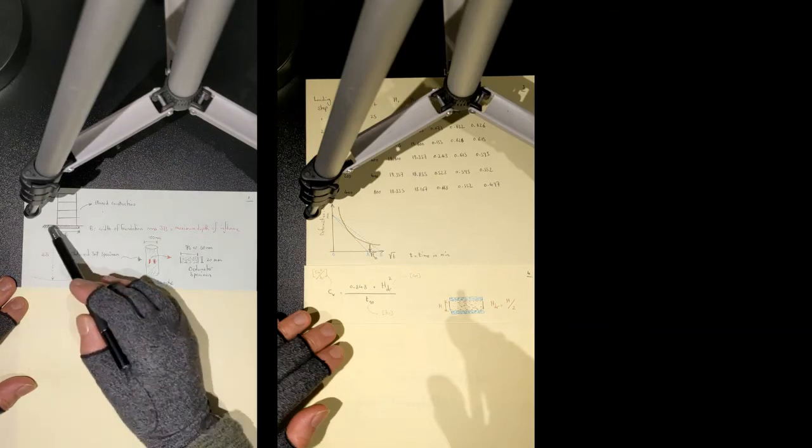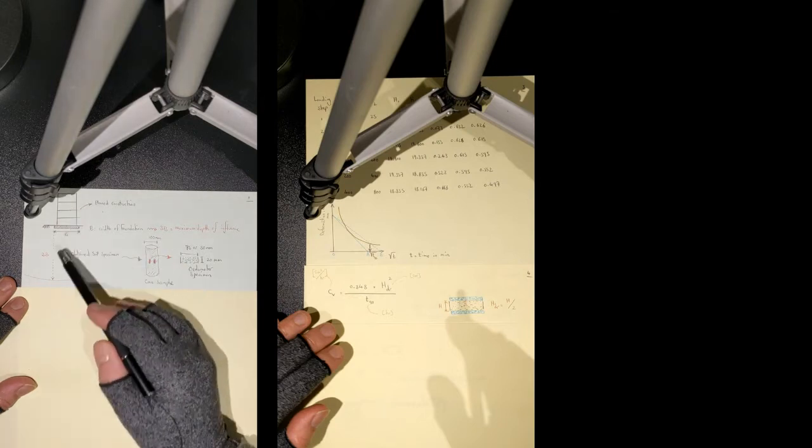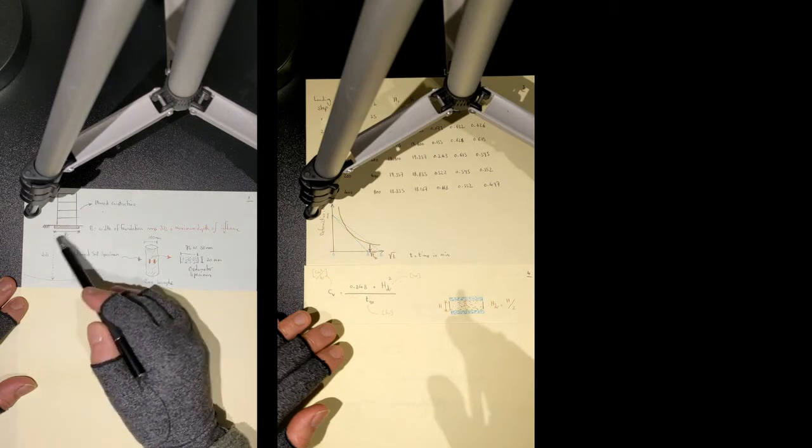and the deepest point in the very bottom of this circle has a distance of 3 times B from the bottom of the foundation. And all this area within this zone, which is confined between the perimeter of this circle and the bottom of the bed of your foundation, is known as the zone of influence. It means that the effect of construction on the ground level will impact the stress state only within this zone. Now, this means that if you have a cavity at a depth more than 3 times B, then you really do not have to be worried about that cavity.